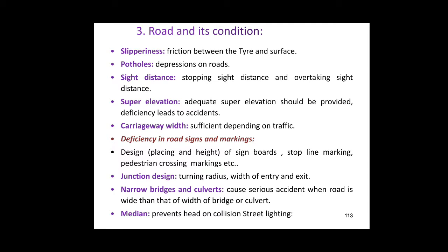Superelevation: adequate superelevation should be provided in order to avoid the lateral skid of the vehicle on the curves. The carriageway width: sufficient width should be provided depending upon the traffic, in order to provide utmost width for the lane so that the vehicles can move with ease.